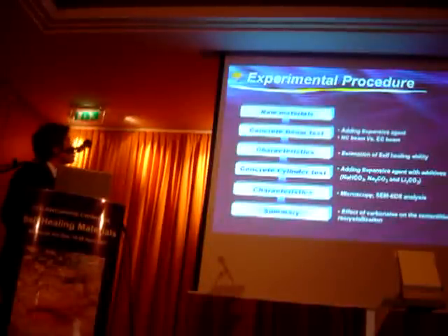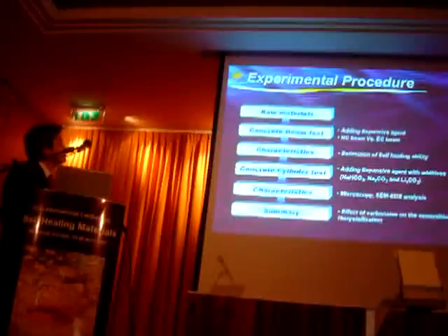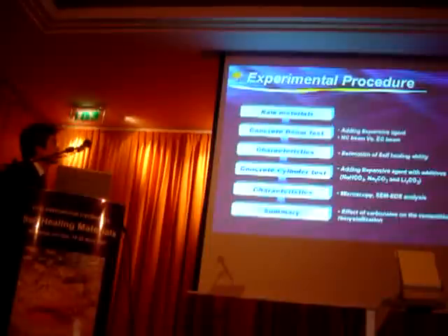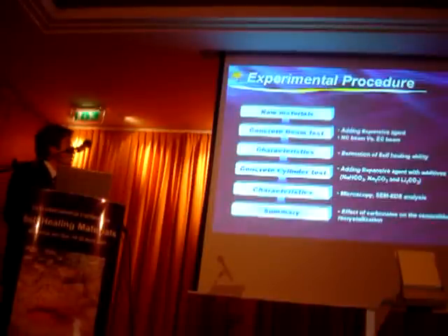This diagram schematically shows the experimental procedure. First, we investigated concrete beams incorporating expansion agent compared to normal concrete beams at a low water to binder ratio. Then we also investigated concrete cylinders using various carbonates such as sodium hydroxycarbonate, sodium carbonate, and lithium carbonate. We also investigated the effect of the carbonates on cementitious recrystallization in this research.